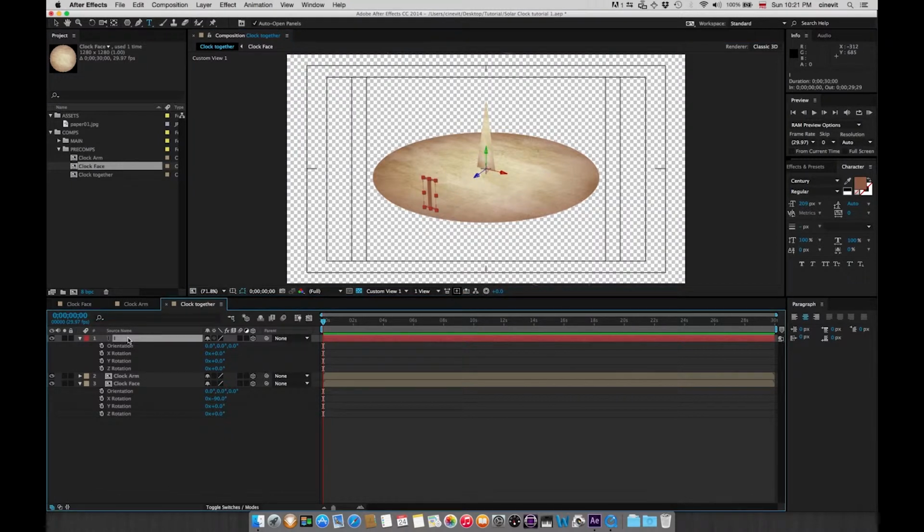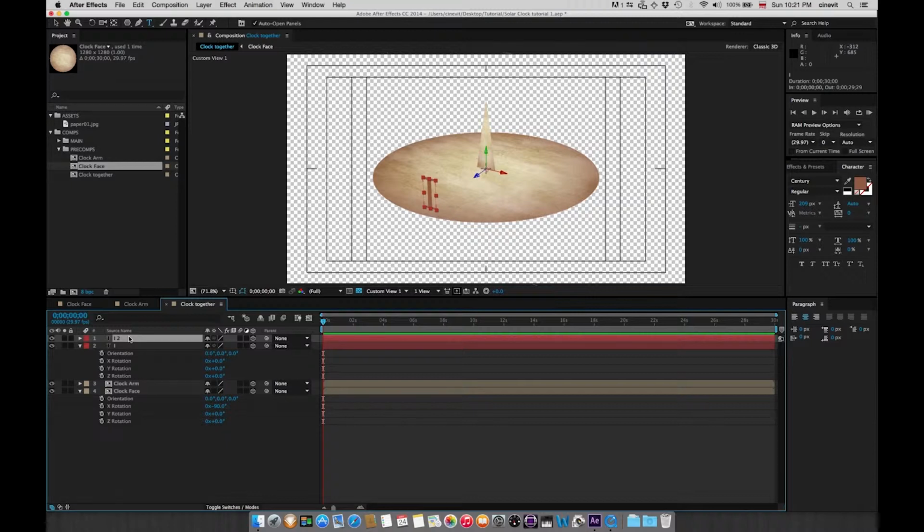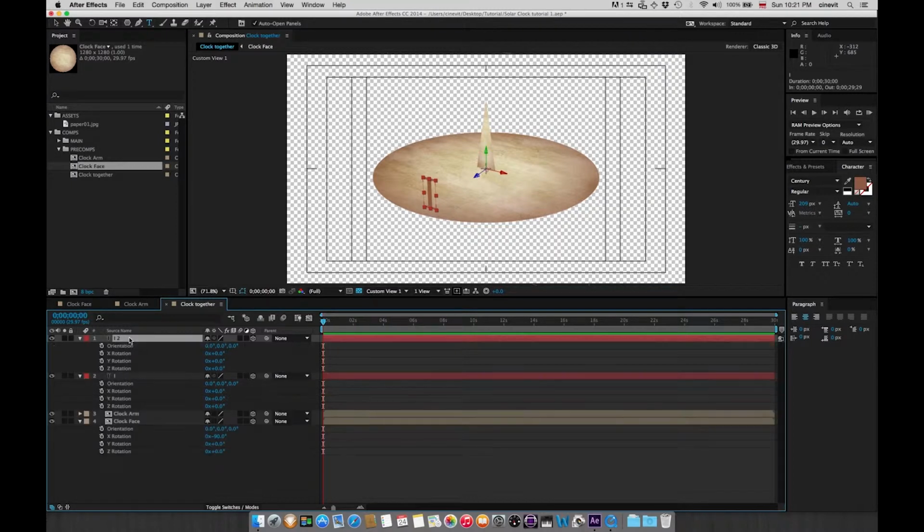Let's duplicate it, and it's gonna be R for rotation. Press R, and we're going to offset the Y rotation. So basically what we are doing, we are rotating it on the Y axis, which stretches from the bottom to the top, and the rotation is around that axis. I'm going to go to Y here, and all we need to do is just basically type in 30.